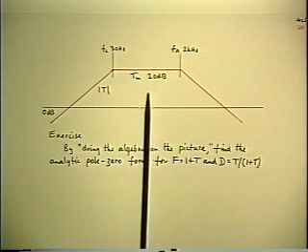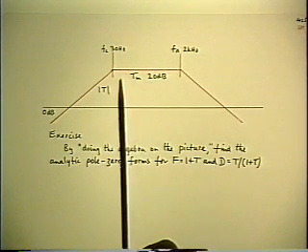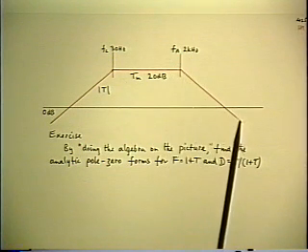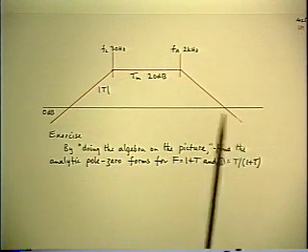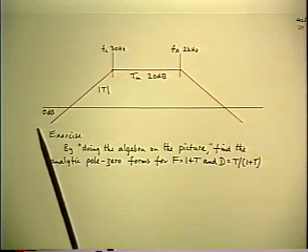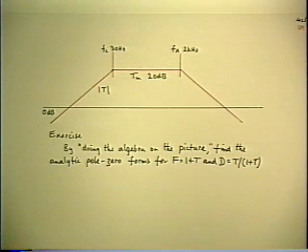The magnitude asymptote graph for the loop gain has Tm of 20 dB mid-band, falls off above the normal pole at 2 kilohertz at the high end, falls off below the inverted pole of 30 hertz at the low end. So this is the first major result for the amplifier loop gain.